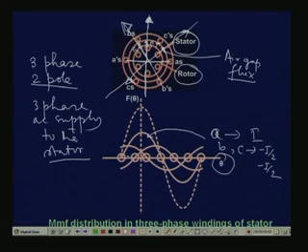So, this is the MMF for the A phase, this is the MMF for the B phase, and this is the MMF for the C phase. Okay. So, these are the 3 MMFs, pulsating MMF. So what is the net MMF? The net MMF in this case is this one, which is nothing but the resultant of these at this point of time.